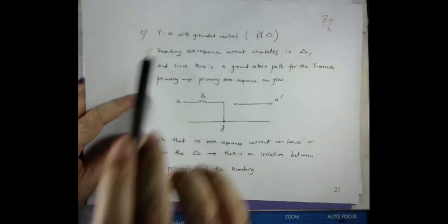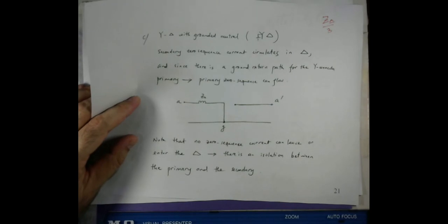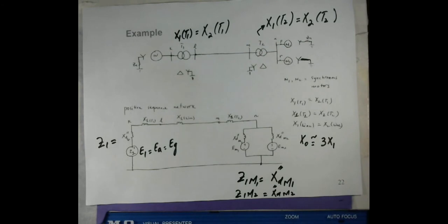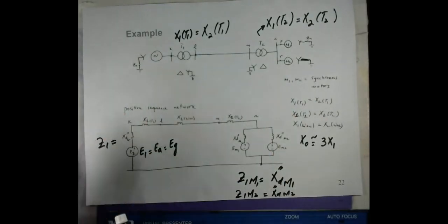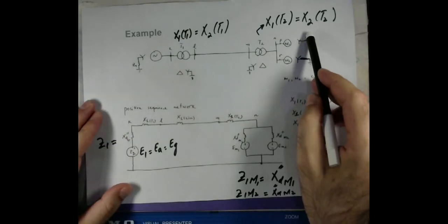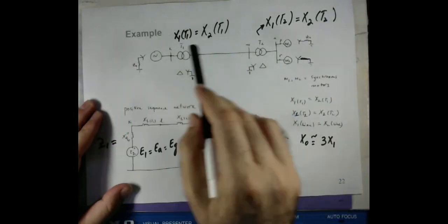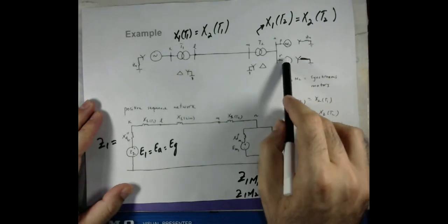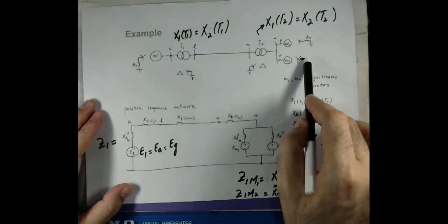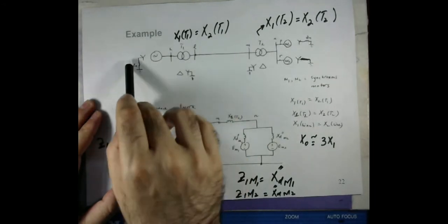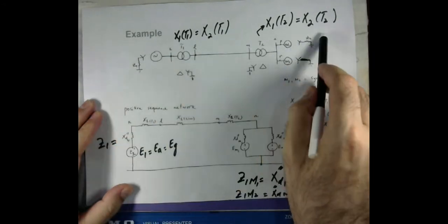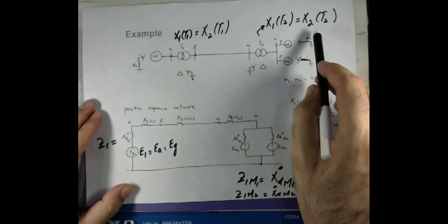So now taking this into account, and also taking into account that the zero sequence impedance of the synchronous machine will now also include this term Zn in these two cases, because in the case of the second motor here the impedance to the ground is 0, but in case of the generator and also in the case of the one motor there are impedances to the ground.